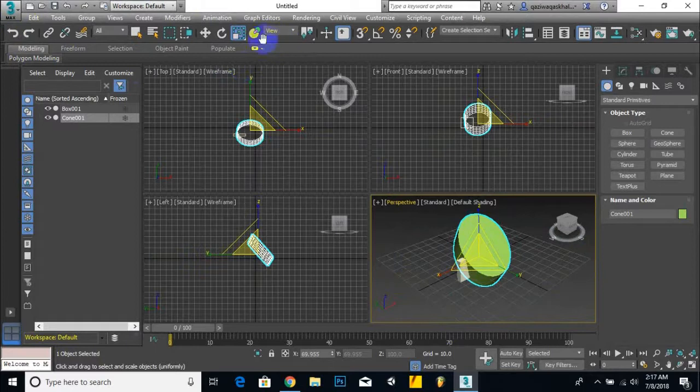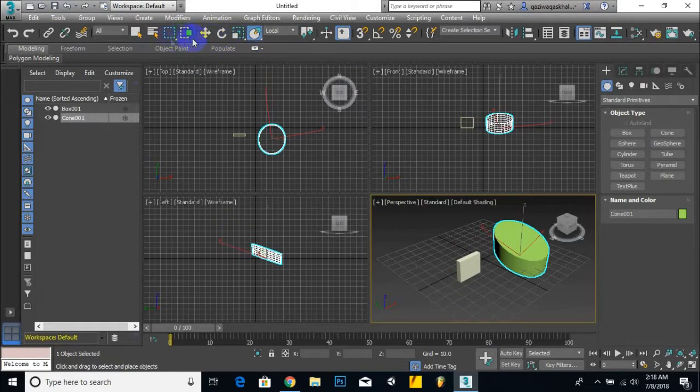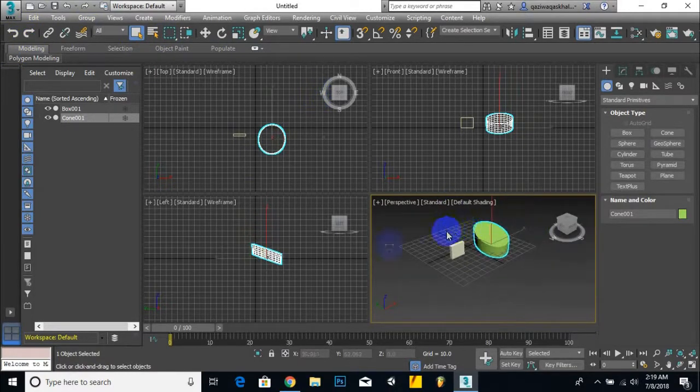And after that, there are tools like viewport. We are now in a default state and we can enjoy different views. There is a selection of Q, W, E and R. These keys are very important, so you should know that. You can place your fingers on Q, W, E and R. So R is for scaling, E for rotation, W for move and Q for select. So these are the very basics in 3D Studio Max, which we have discussed in this video.